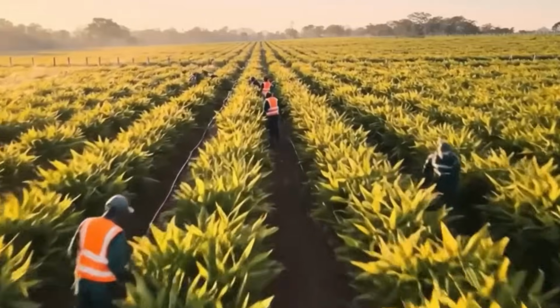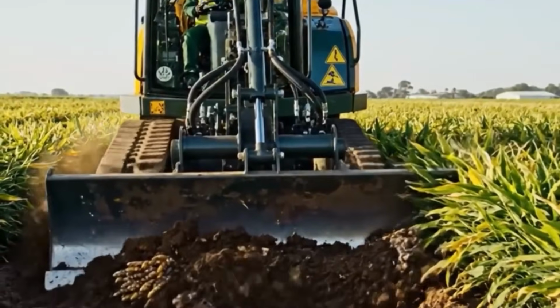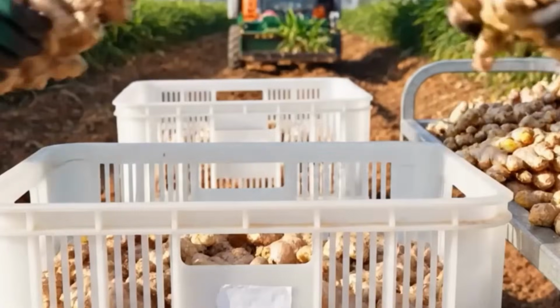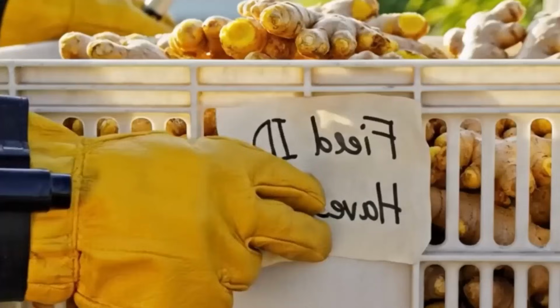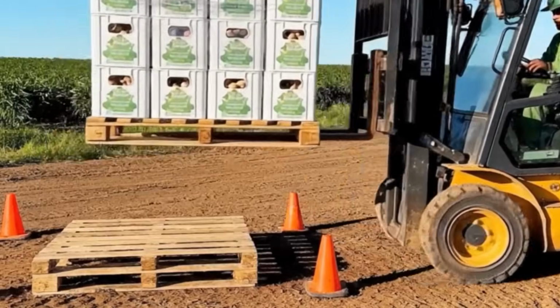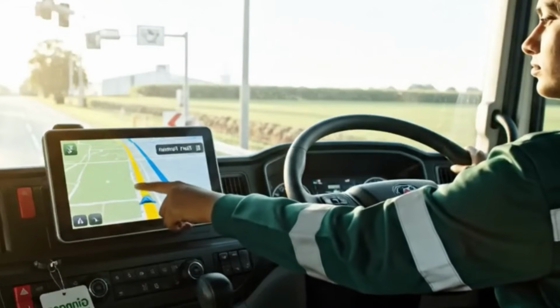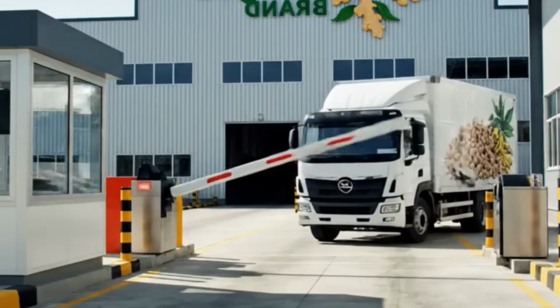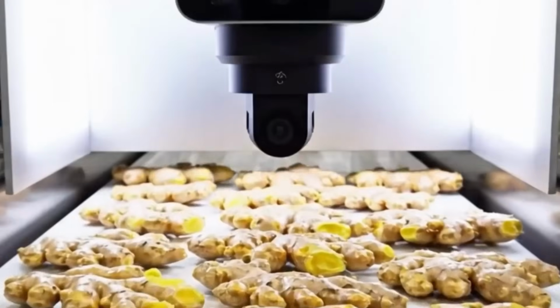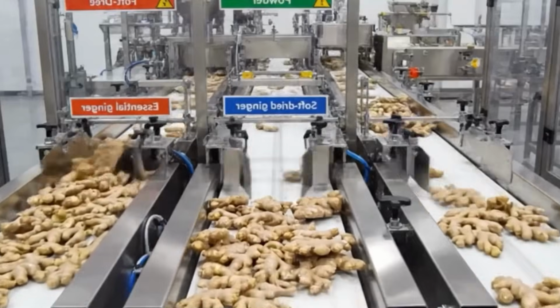Parallel to this, the syrup production begins in a closed system syrup room. Liquid sweeteners, such as high fructose corn syrup, are delivered in heated tankers and pumped into bulk storage silos lined with food-grade coatings. These silos are equipped with volumetric flow meters and thermal controls. The sweetener is metered into stainless steel mixing vessels using precision dosing pumps.